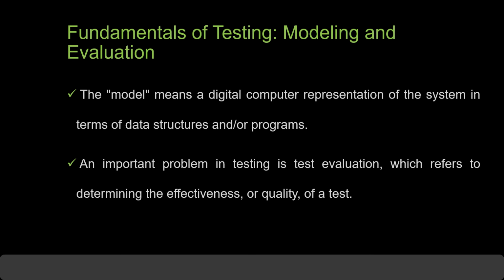Moving to another fundamental of testing, which is modeling and evaluation. First, we'll discuss modeling. Basically, as design errors precede the fabrication of the system, design verification testing can be performed by a testing experiment which makes use of a model of the designed system. In this context, model means a digital computer representation of the system in terms of data structures or programs.